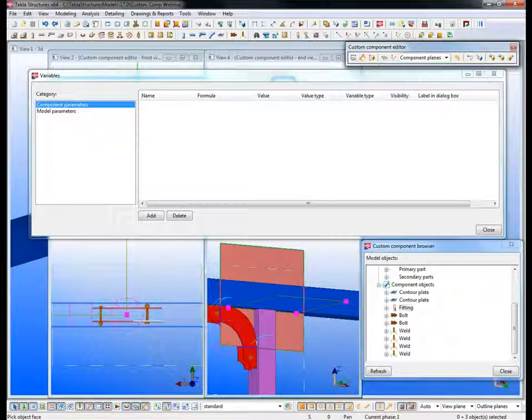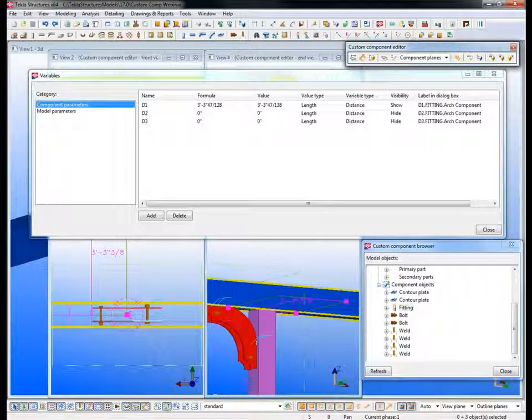So I'm going to go ahead and bind this to this plane right here, all 3 of these. So I'll just click, and you'll notice that it adds in D1, D2, and D3. These are the bindings for each of those handles. D stands for distance, so these distance variables are created by binding. There's also something else you could see in here called a parameter, which would be P1, P2, etc., which will be added using this button, which will allow us more functionality and flexibility within our actual components. So when we get to that stage in the game, I'll discuss that more.